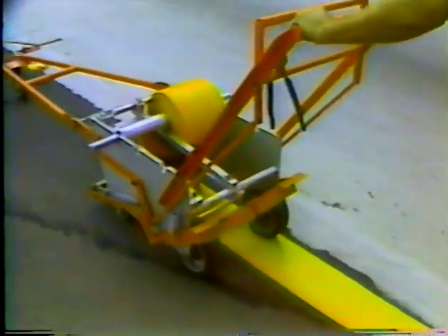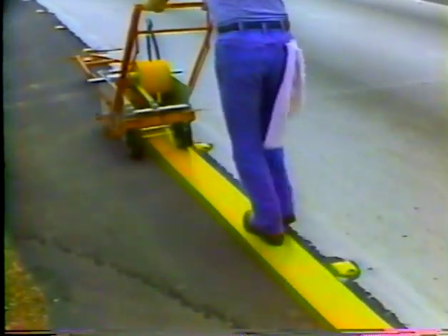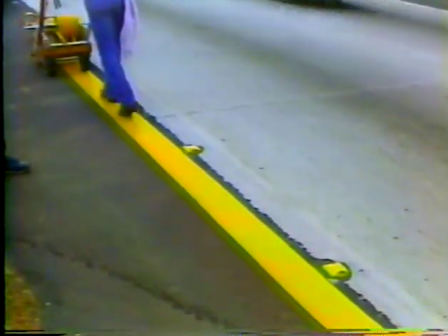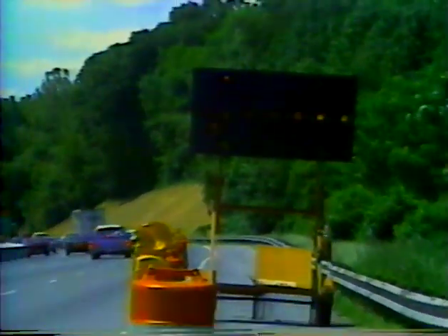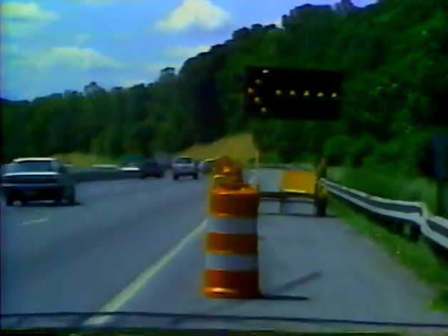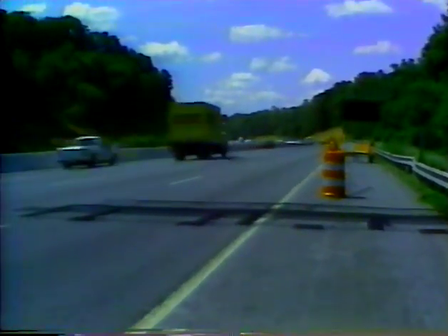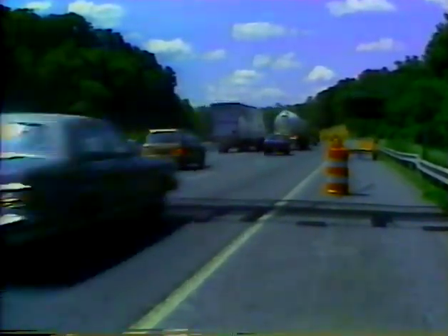Even after removal, old markings are often visible enough to confuse drivers, especially at night or in wet weather. The contractor can compensate by using wider temporary lines, raised pavement markers, or a tighter spacing of channelizing devices to give drivers better guidance. Aero panels in work zones also require placement consideration. They're most effective when they're placed on the shoulder at the beginning of the taper. On roadways with little or no shoulder, they need to be placed further back, but the closer you can get them to the start of the taper, the better.